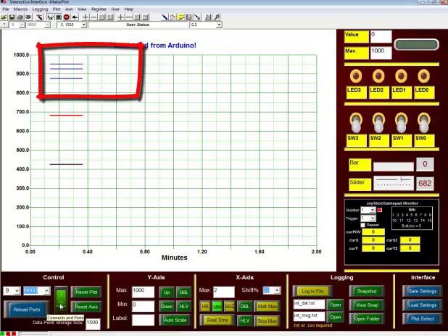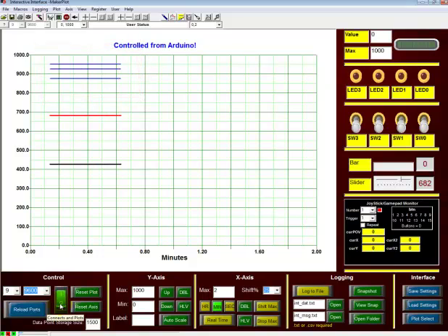These are our digital values. The top value is whether the set point has been exceeded or not. Right now it is a 0 and it hasn't been exceeded. The other 2 values are the decrease and increase push buttons, SW1 and SW2. The red line is our set point, and our black line is the potentiometer value.